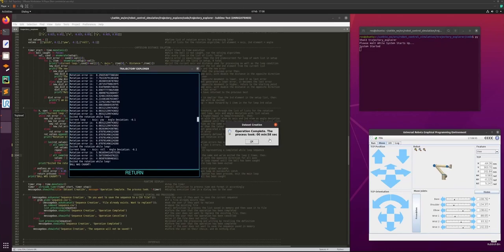It is important to note that throughout these 58 seconds there's always a 2-second delay between every single MoveJ movement. So once I'm informed about this, I can just press OK, and then it asks, do you want to save the sequence to a CSV file? Yes, I do. I have added edge cases. In this case, we have an actual file already present, and it asks, do you want to replace it? Because it already exists.